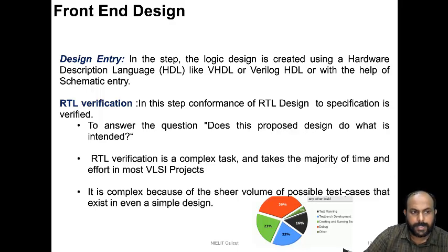Design entry is, as I told, representing the design with the help of hardware description languages, and RTL verification is all about finding the answer to the question of whether the proposed design will do what is intended by the customer or not. RTL verification becomes a complex task out of the sheer volume of test vectors or test cases that the verification engineer has to apply on the design, so as to verify it as exhaustively as possible.